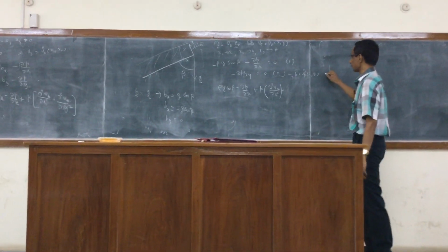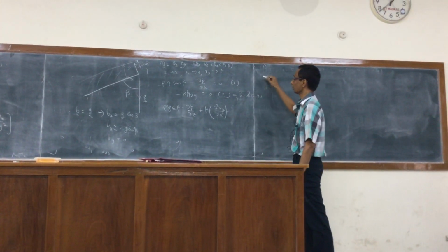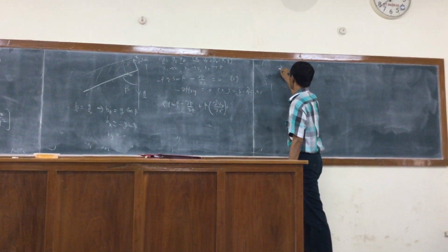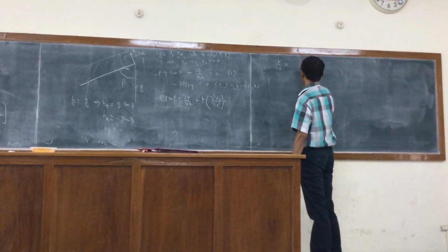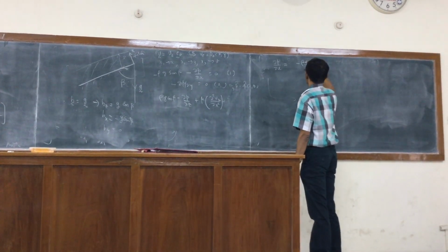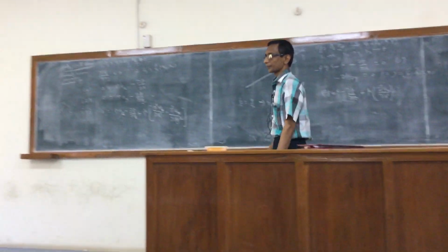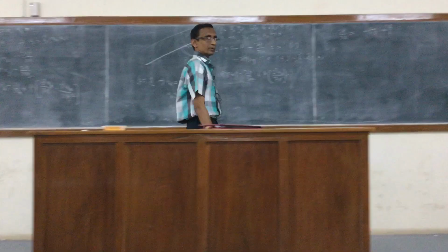So from this I get that Vz has to be dependent on x only, and is independent of y. If I use that here, then I get dP/dx is equal to actually a constant. That's a constant, so I can integrate this.